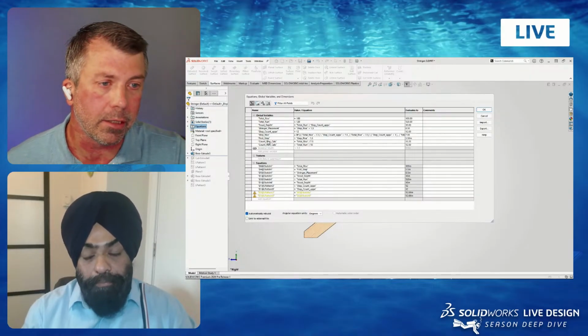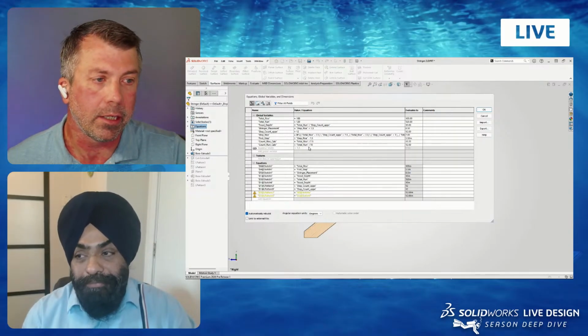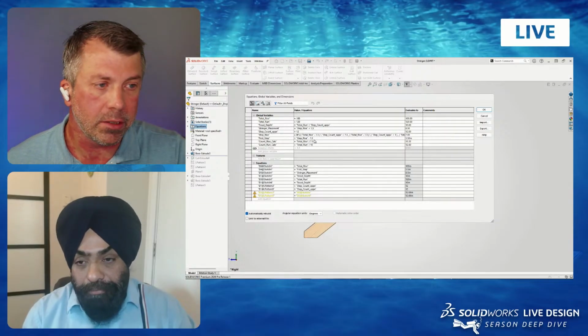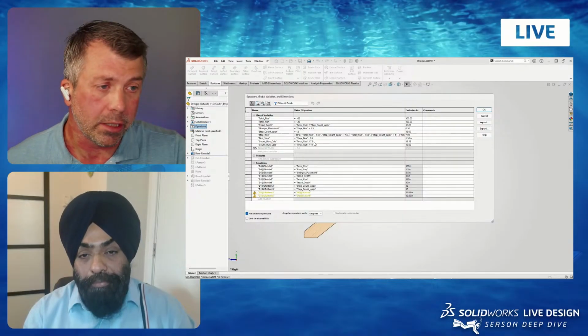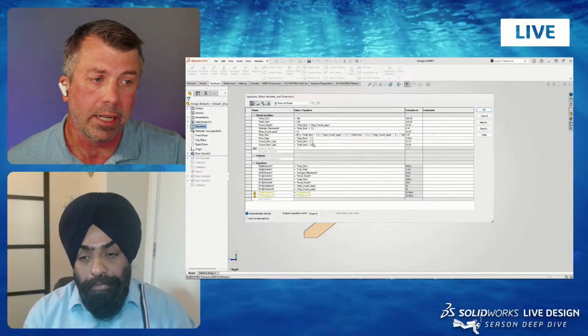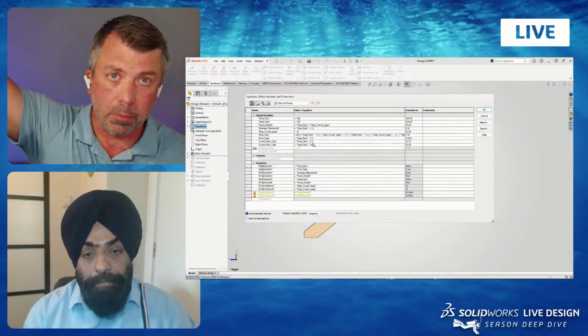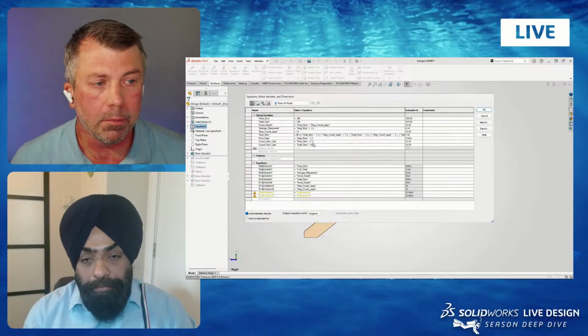So if you look in here, we have my count rise calculator and count run calculator. These are based on construction standards. You can't go above 7 3/4 inches. So I said, let's shoot for a goal of a 7.5 inch rise per step. Have you ever been on steps that are super high? No, they're all within a normal height that we can walk up.